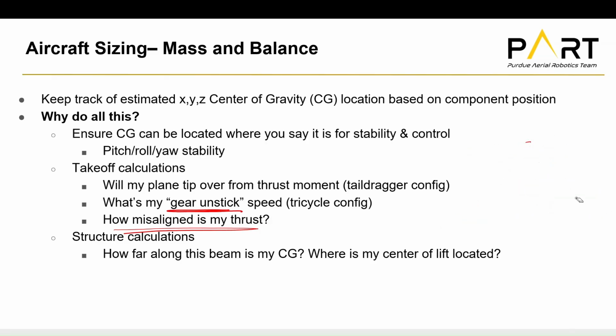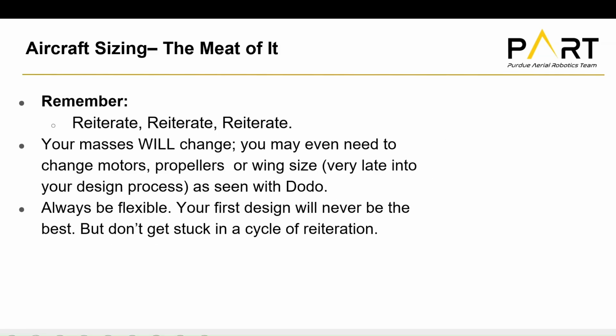Okay. And also structure calculations, right? If you do a boom or something, or for a fuselage, right? You have to know how far along the boom is your center of gravity, where's your center of lift, and how are those going to interact in terms of structures. Okay. So remember, you have to reiterate constantly. Your masses will change, and you may even have to change motors, propellers, or wing size.